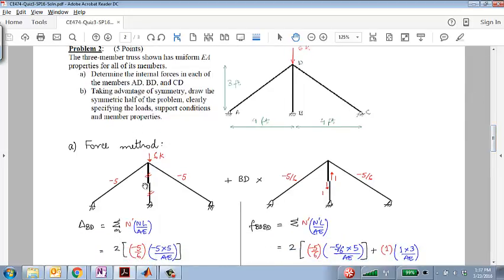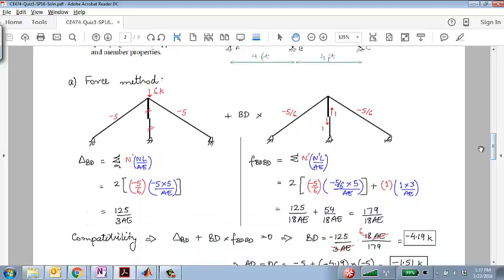And this is an important point that I'll emphasize again. I saw that some of you, instead of just cutting it, completely removed that member, which is incorrect. You're not removing a member, you're simply cutting the member and trying to measure the displacement, either overlap or separation, at the cut. And in order to do that, you would then typically be using the virtual work method. You apply unit loads at the tip of the cut, and you find the virtual internal forces times real displacements.